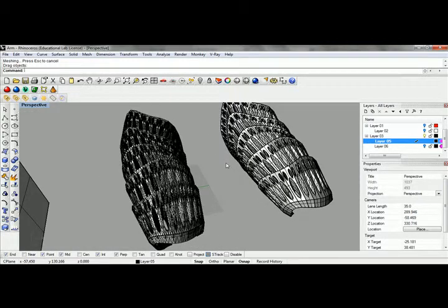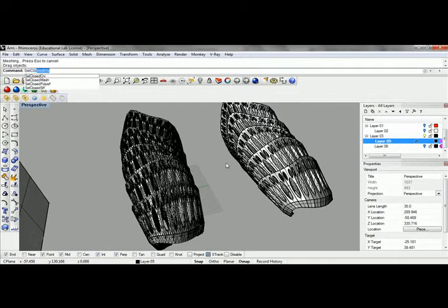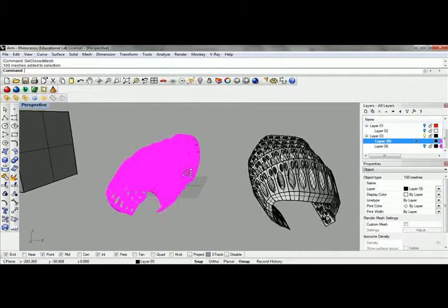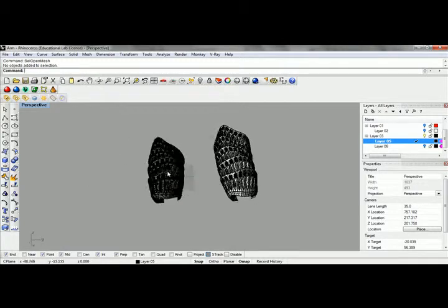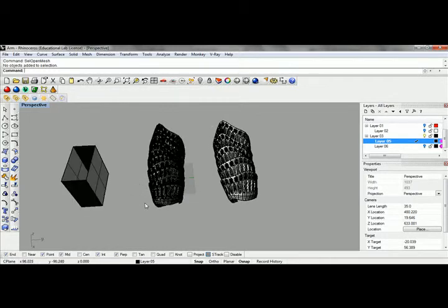All right, so now we're going to run the same set of tests to make sure that this is still a 3D printable object here. So I'm going to do select closed mesh. That's a good sign. The vast majority of our geometries are in here, and we'll try this again. We'll select an open mesh just to make sure. And it says no mesh objects were added, so we're in really good shape. This is essentially ready to be exported to the 3D printer here.